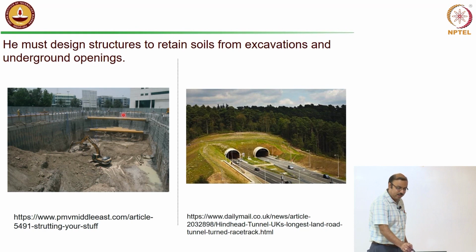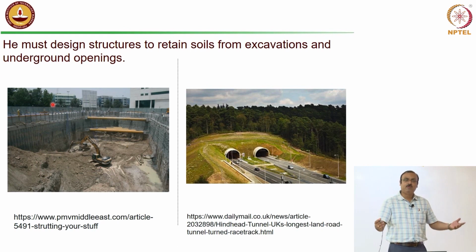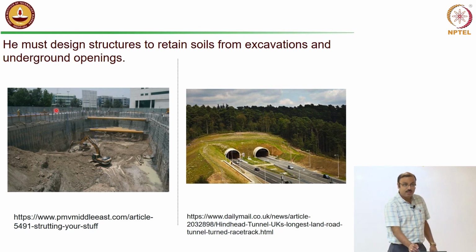So, if this wall is not there, what will happen? The soil from the back side will start caving in the excavation zone. You may think, what is the problem? Okay, it may cave in, then I may remove it after some time, then again continue. No, if the surrounding soil is caving in, what about the surrounding structures?